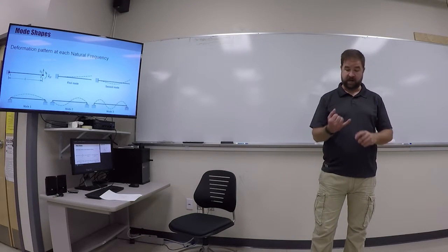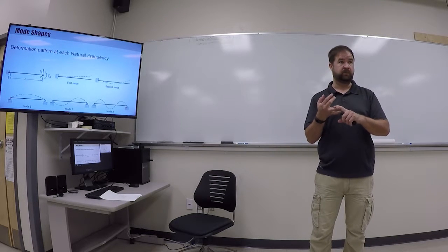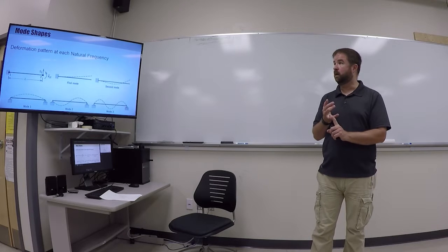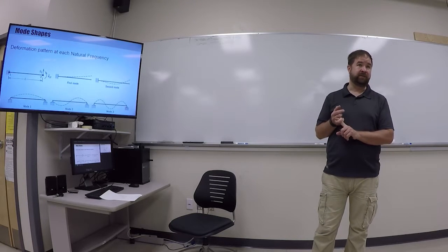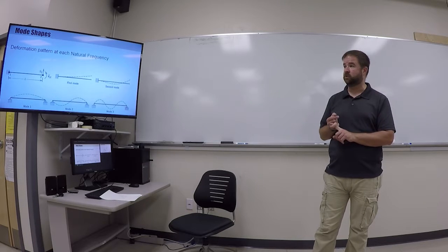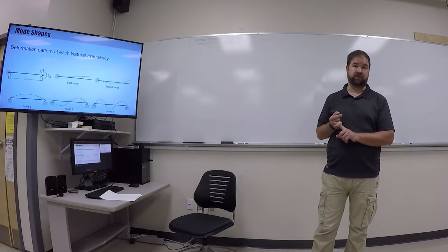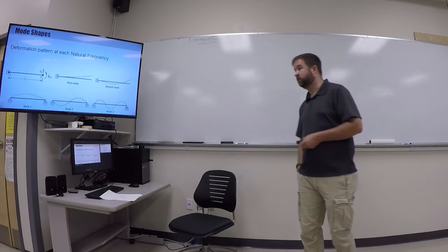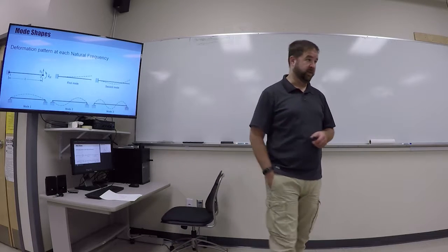Why do we care? Sometimes we want to avoid them. In rare instances, we actually want to tune to them. And then the other side of this is mode shapes. Mode shapes are the shapes that the structure displaces into at the various natural frequencies. So for every natural frequency, there will be a mode shape associated with it.